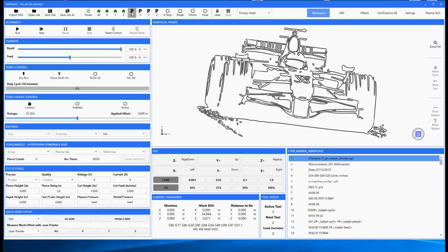Now, notice as I move the cursor left or right, there's a gray background on these buttons. But if I go over e-stop, there's no gray background. In order to conserve real estate so that we could get more information on the screen, we've had to consolidate action buttons with indicator buttons. So right here, e-stop, there's no gray, which means it's not an action button. Gray indicates that you can click it and it will do something. This is an indicator. Obviously, e-stop, the last thing you want to do is override e-stop, so there's no way to do that.